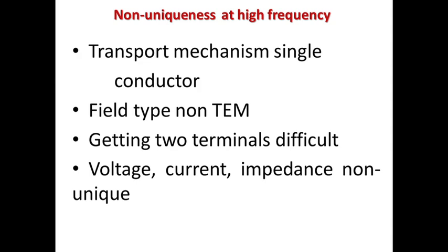A single conductor does not support a transverse electromagnetic or quasi TEM type of wave. So, the field here is non-TEM, mainly in the form of various combinations of transverse electric and transverse magnetic modes. And in a single conductor like a waveguide, it is very difficult to get two terminals to define voltage or current.